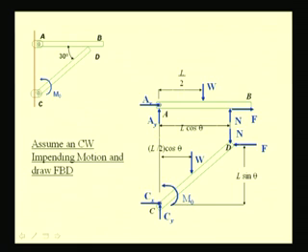So, the force is marked from B to A. On rod AB, this force will be equal and opposite, so it is marked from A to B, and we have the pin reaction at A, the weight of the rod, and the normal reactions as the other forces in the free body diagram. So, from this, let us write the required equations to find the unknowns.